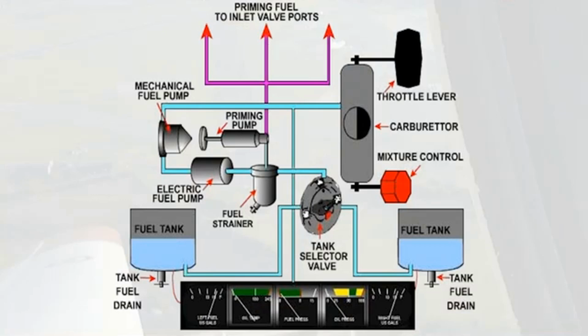A simple light aircraft fuel system is shown here. The fuel is contained in two wing tanks, each of which we have seen has a quick drain fitted at its lowest point. Fuel quantity is gauged by a simple float-type sensor and is shown in the cockpit on two separate dials. Float-type sensors are fairly unreliable, except either on the ground or in prolonged straight and level flight. So, before flight, always visually check the fuel contents by removing the tank filler caps and looking into the tanks to make your own assessment of the quantity.